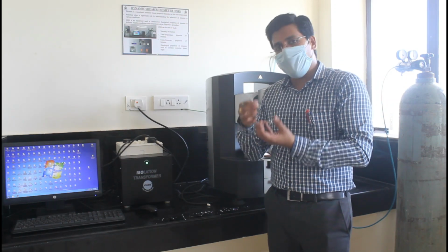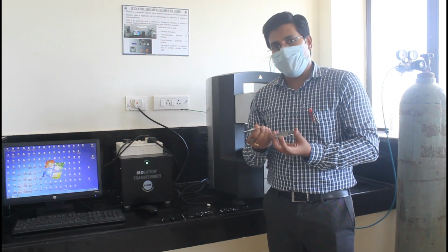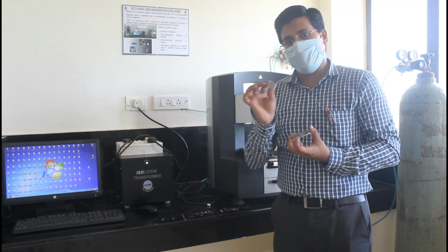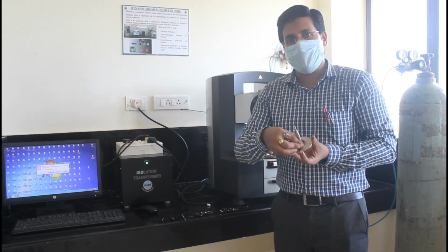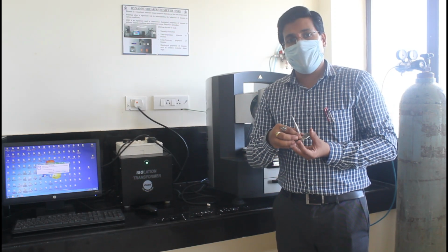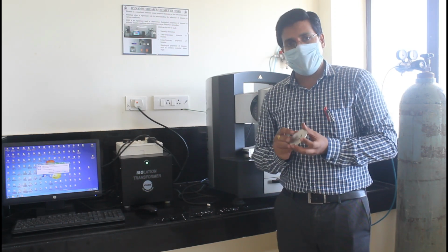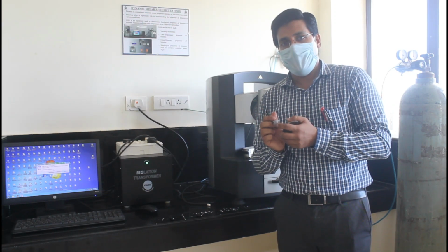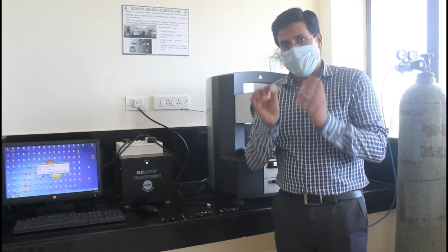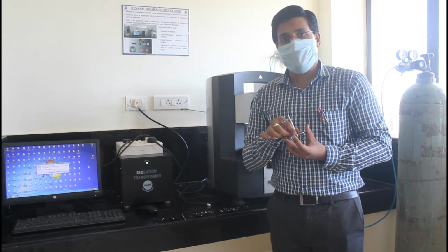Similarly, if you go for a PAV-aged bitumen, what will we do? We will reduce the diameter to 8 mm, because with PAV-aged bitumen, a thicker, bigger sample can undergo breaking since it is very stiff. So we reduce the size to 8 mm diameter and the spindle diameter will also be 8 mm, and the sample thickness will be 2 mm. In the 25 mm case it will be 1 mm sample thickness.